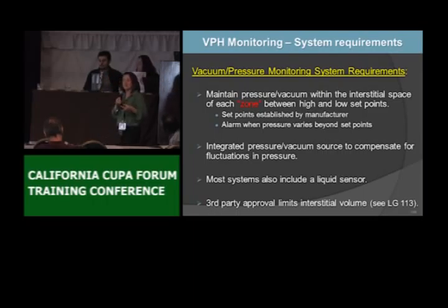And I'd say on average you have anywhere from 7 to 10 zones. And I'll show you, next slide shows that example of a zone. So each vacuum sensor or pressure sensor is really only capturing a small portion of your system. Okay, so you want to maintain that pressure or vacuum of each zone. That's how you're going to tell if you have a leak or not.